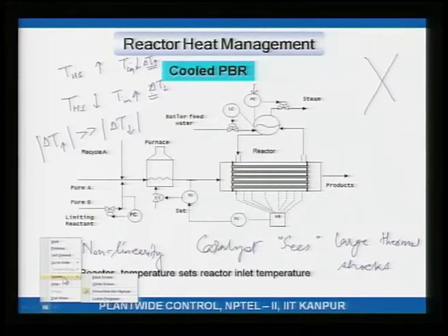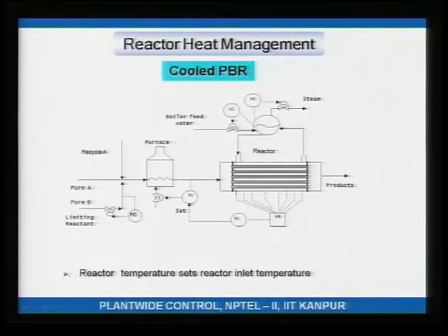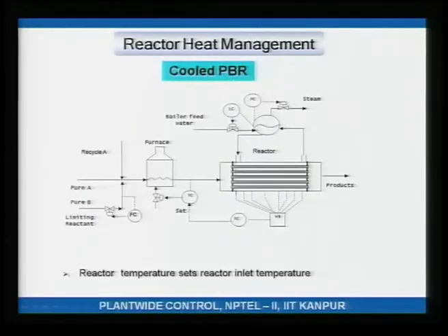Another thing that I wanted to highlight in this scheme was reaction heat. In the previous scheme, if the temperature is increasing, I was adjusting the cooling rate. In this scheme, if the temperature is increasing or decreasing, I am adjusting the amount of heat that gets generated. You see, so in this case it works by Q gen. So, T hotspot is controlled by adjusting the amount of heat that is getting generated due to reaction. Q cool is not getting manipulated. Okay. I hope this difference is clear.